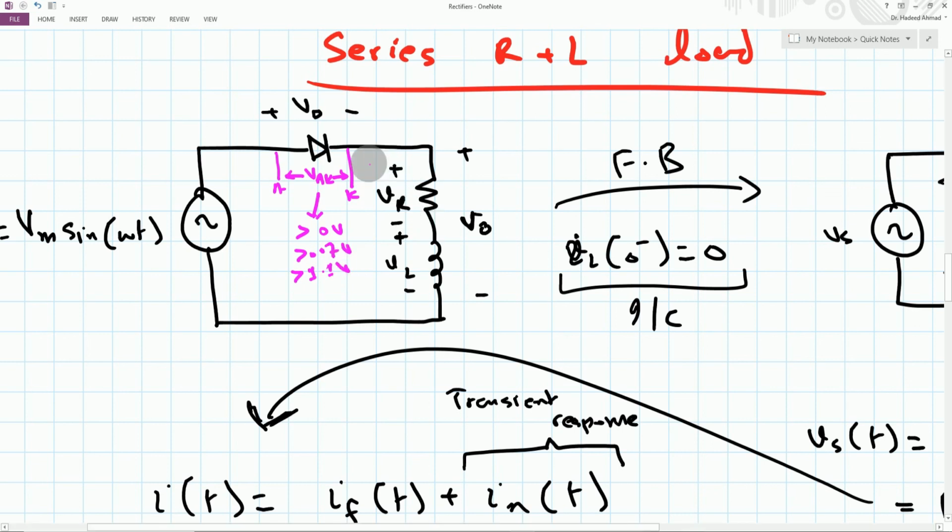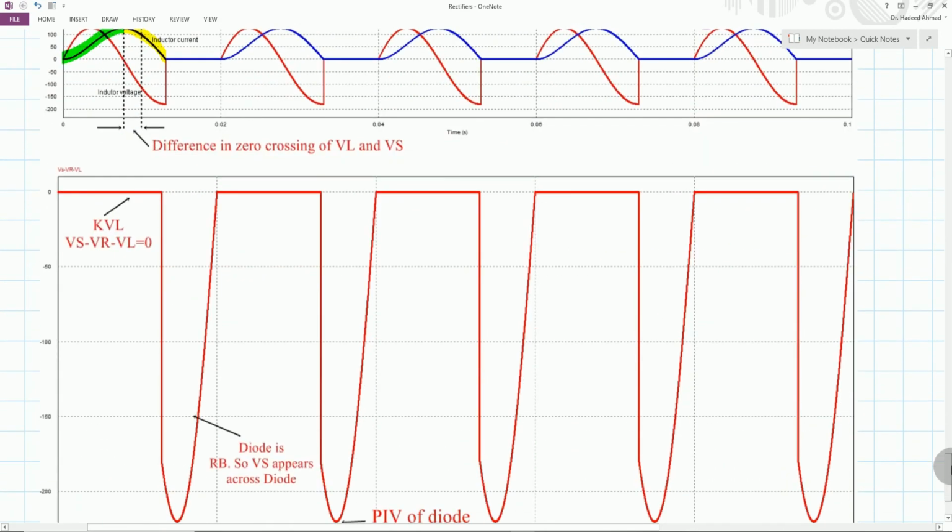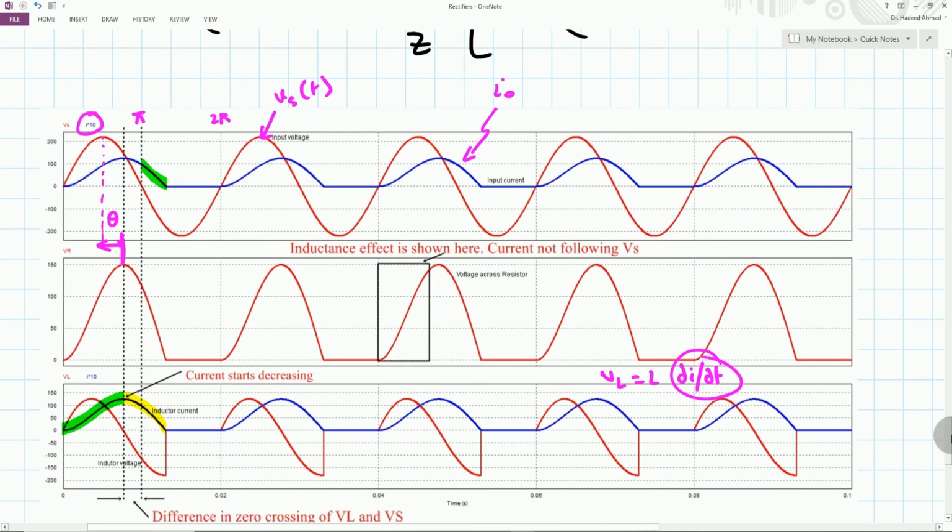So right after the pi time, you see that this VL is enforcing enough negative voltage that the cumulative anode to cathode voltage for this diode remains above its threshold values, and consequently it conducts beyond the positive half cycle, thereby connecting this voltage source Vs to the load for the duration which ends at this particular time instant that I will call beta.